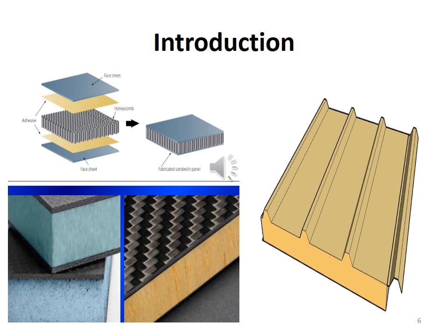You can see here a typical example of a sandwich structured composite material where the two stiff skins are joined together with a lightweight thick core. The core material is normally low strength material, but its higher thickness provides the sandwich composite with high bending stiffness with overall low density.